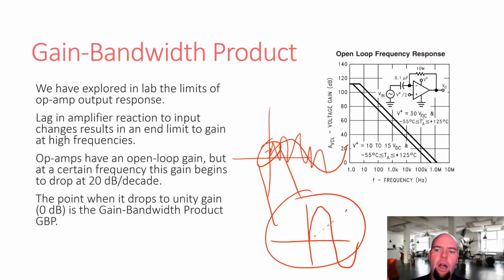So op amps do have a frequency output limitation, but it's not just a frequency limitation. Let's say you took the same frequency and you decreased its amplitude. If you decrease its amplitude enough, that same frequency signal would have a lower slope, just by lowering its amplitude.